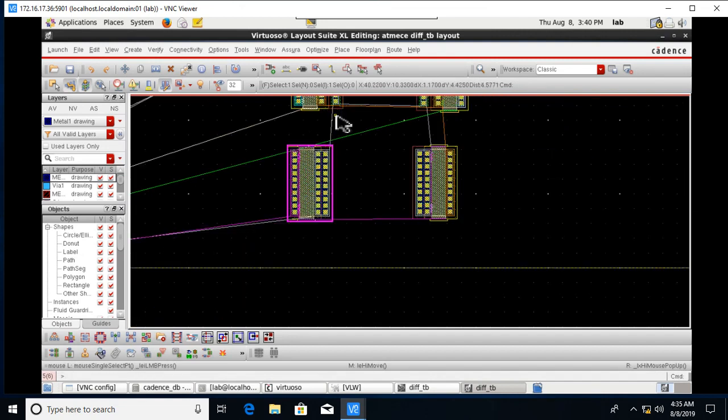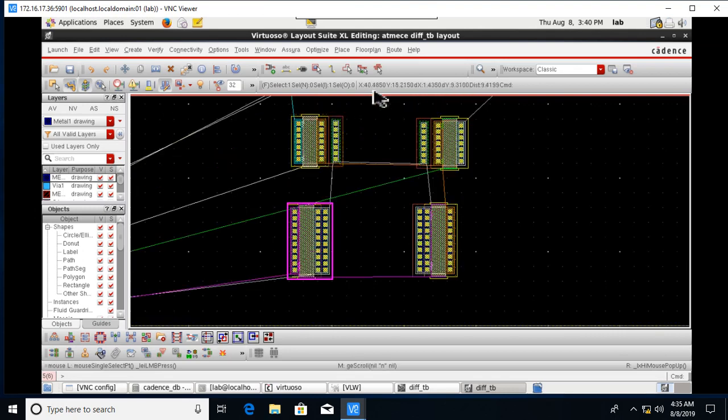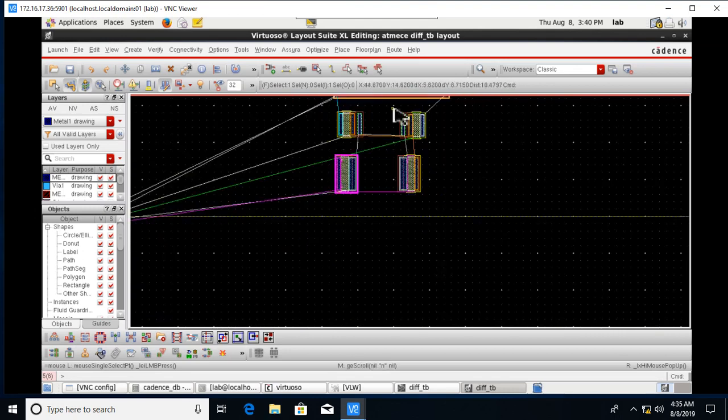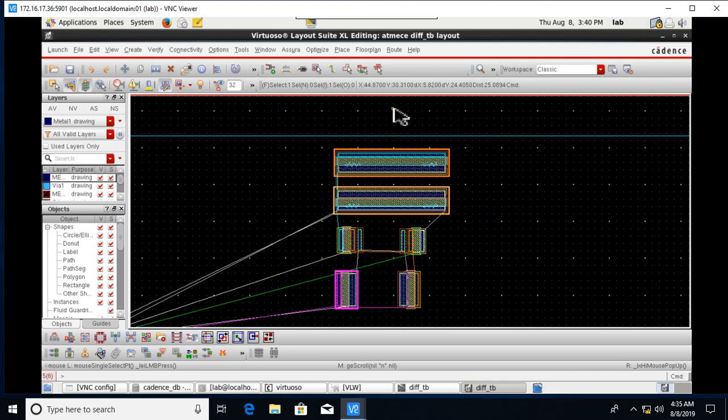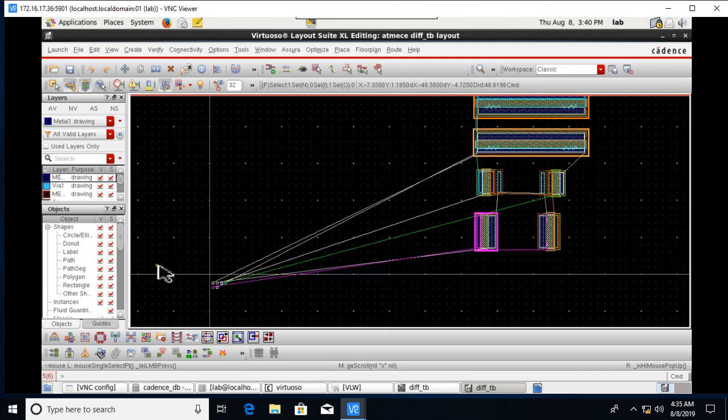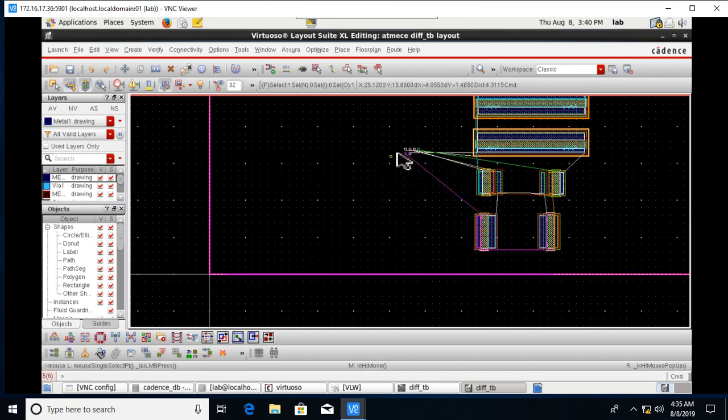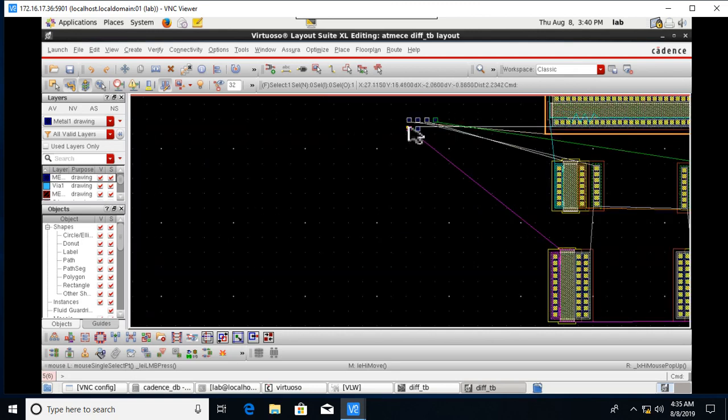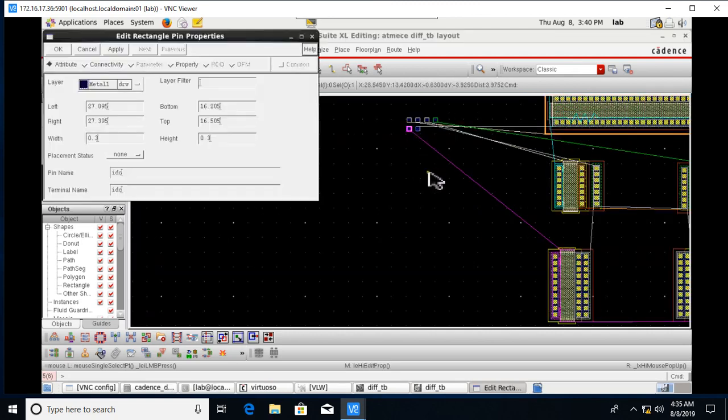After proper placement of the components, now we'll go for the pins. Move it to any one corner as per your comfort and click on each pin. To know which pin it is, just click on it and press Q or go to properties.